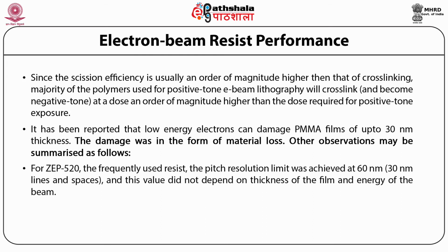First, for ZP520, the frequently used resist, the pitch resolution limit was achieved at 60 nanometer, that is 30 nanometer lines and spaces, and this value did not depend on the thickness of the film and the energy of the beam.